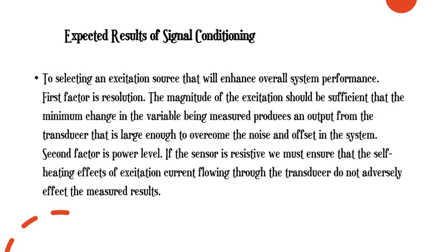To select an excitation source that will enhance overall system performance, we must consider some factors. The first factor we consider is the resolution. The magnitude of the excitation should be sufficient that the minimum change in the variable being measured produces an output from the transducer that is large enough to overcome the noise and offset in the system. Secondly is the power level. If the sensor is resistive, we must ensure that the self-heating effect of excitation current flowing through the transducer does not adversely affect the measured result.